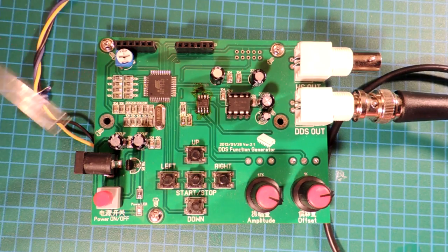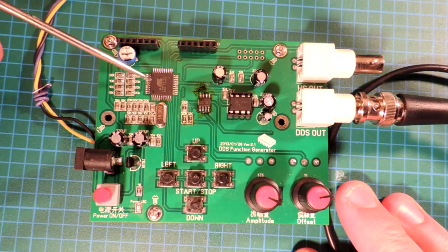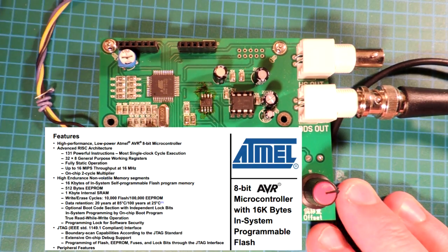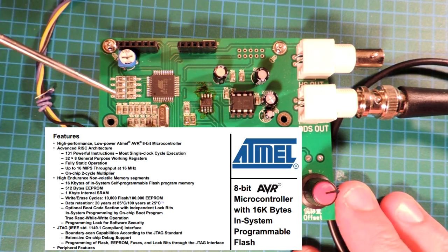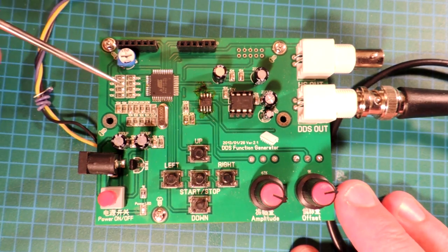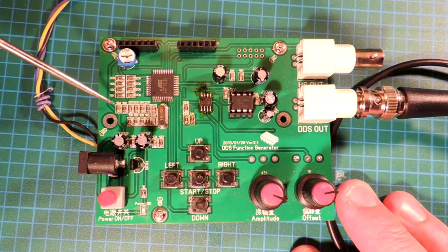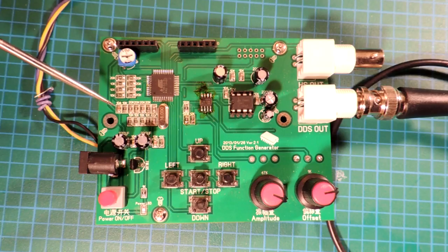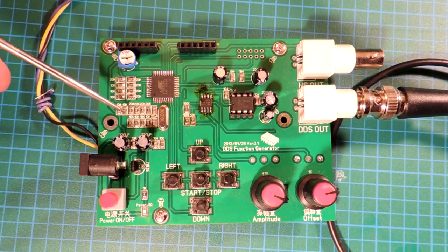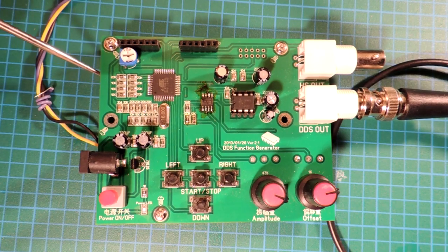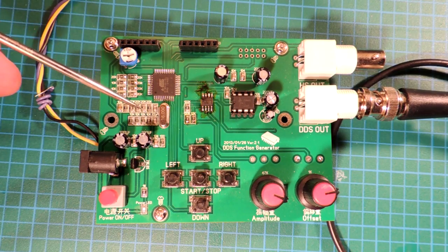Okay, really straightforward topology. Here's a little tiny microprocessor, I'll pop up the data sheet. Basically, it just thrashes away as hard as it can to create the waveforms. That's why the keyboard becomes non-responsive when it's generating. You see a lot of resistors here. It's basically an R2R divider, so they're not using any sort of internal D-to-A converter. They're converting it with these resistors here. Again, pretty weak because obviously these components will have tolerances, and that will result in all sorts of strange artifacts.